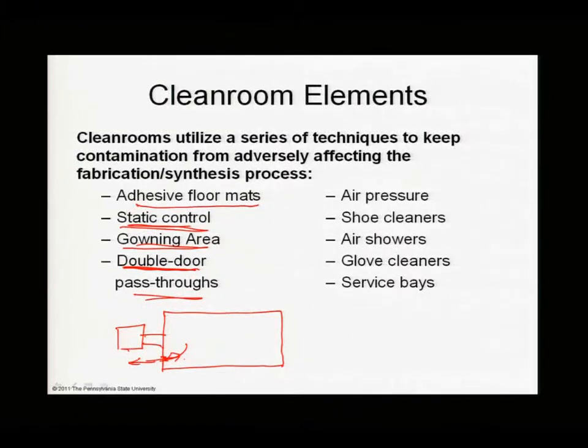So you need these sorts of things. You of course have to worry about fire escapes and door arrangements. Then you also have to think about making sure the doors are big enough to be able to bring equipment in. So you need some doors somewhere for both fire exiting and also to bring in new equipment, take out old equipment.